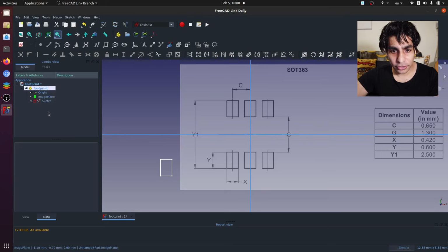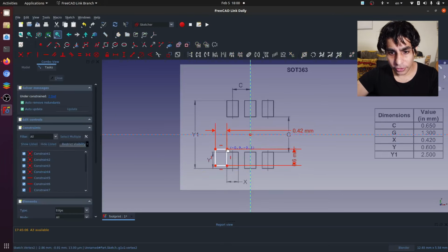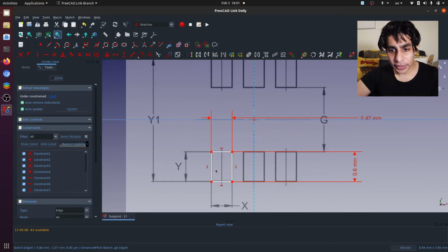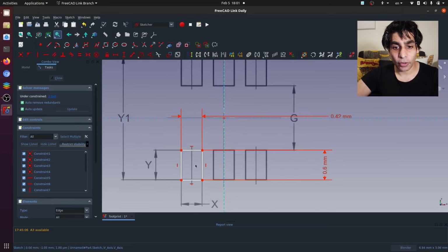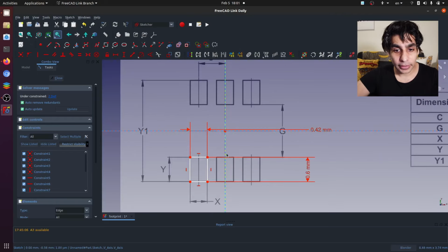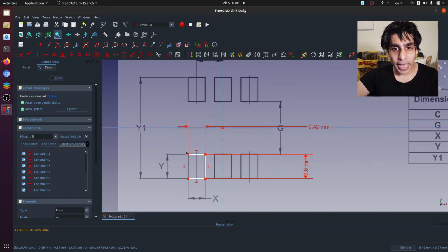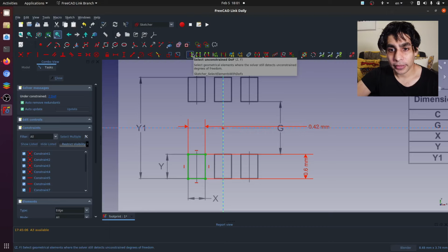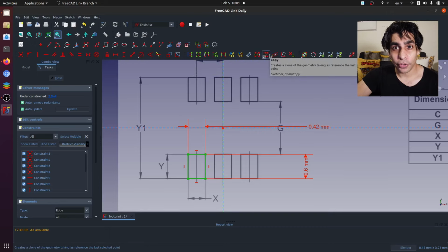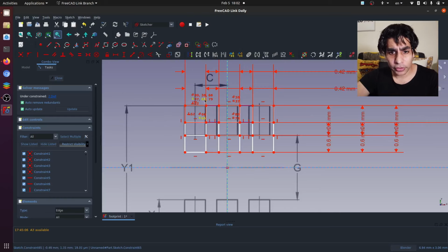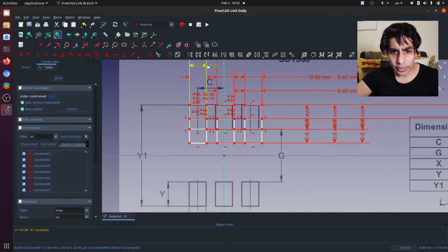So now we can enter our sketch again and we can align our sketch to the right location. And what we're going to do here is we can actually pattern 6 of these since they're all the same size, and that should be a good way to actually get the sketch completed quickly. So we're just going to grab that, and we're going to create a rectangular array. So let's do that. Repeat this process, and voila. What we need to do is just dimension these properly. So let's go ahead and try to do that.